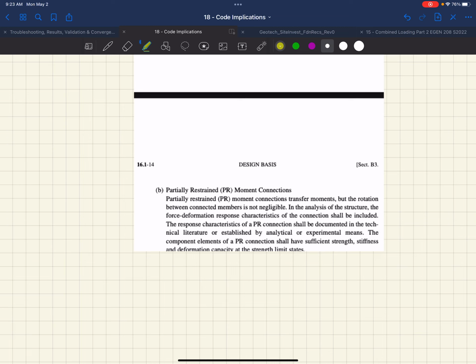And so what they're telling you is they limit the thickness of this. So they're saying at some point, right, when that thickness gets so big that when this beam does get loaded, it acts as this torsional spring. And they just want that torsional spring to be weak enough that as it makes it through its rotation, it's not going to transfer a whole lot of moment. It's negligible, right?